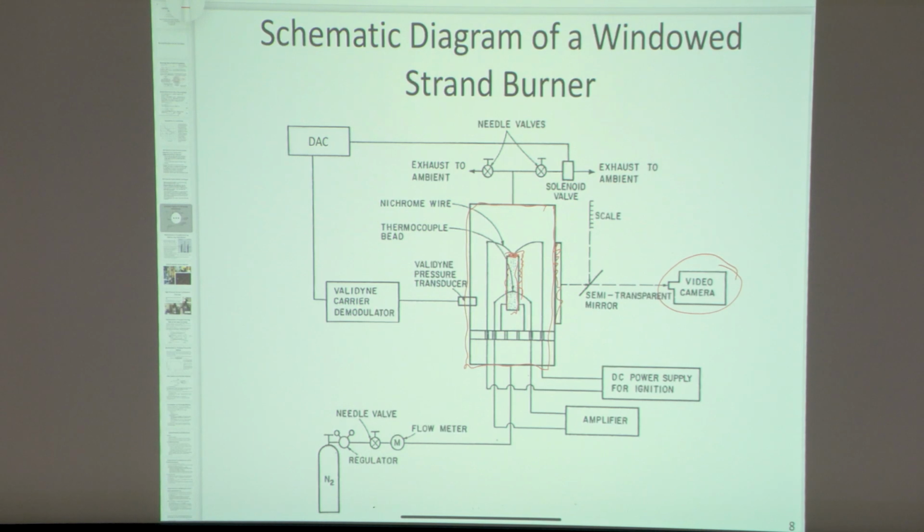Now, the way I avoid that is what I'll typically do is I'll coat the outside surface here with only a fuel ingredient that has no oxidizer in it. Remember, the propellant has fuel and oxidizer. So in that case, it's going to be very difficult for the flame to propagate down here because I'm going to fill this chamber here with an inert material like argon or nitrogen, so there's no oxygen out there. Okay? And that prevents the flame then from spreading down the side.